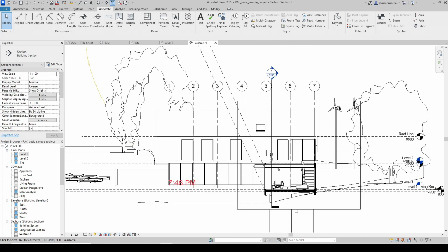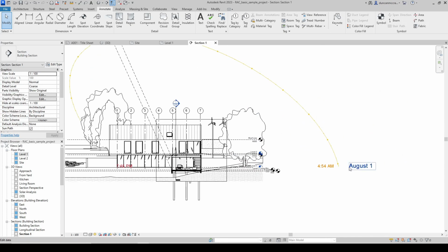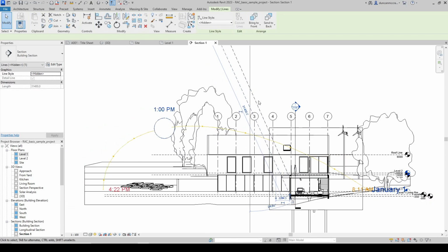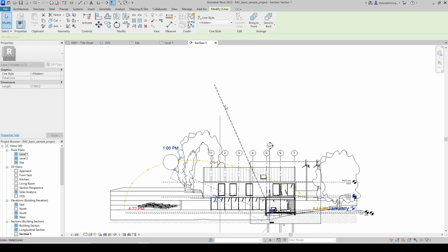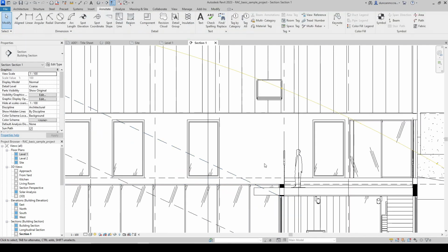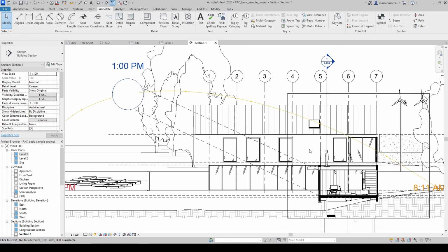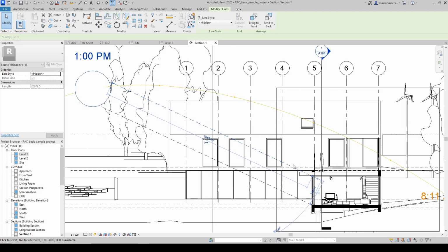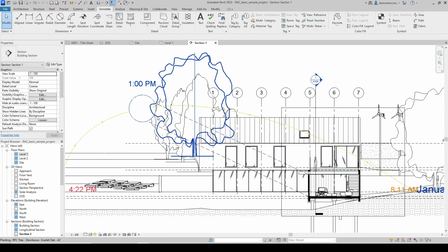And we can see that if we change the day on the sun path to a shorter day, in the winter when we actually want sun coming in through these windows, let's say January 1st, the angle of the sun is much steeper here, right? So the sun is barely blocked at all by this sunshade. So we can minimize the solar gains in the summer with this overhang and still maintain a lot of sun coming through in the winter, which is what we want.